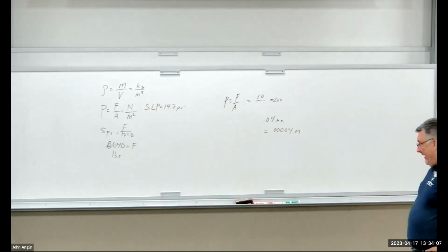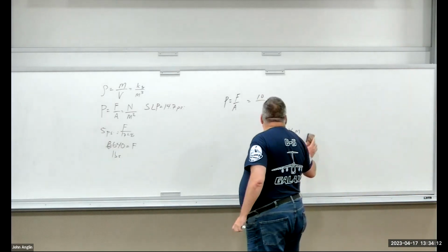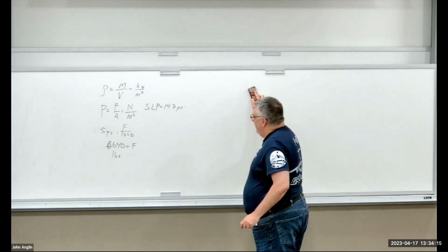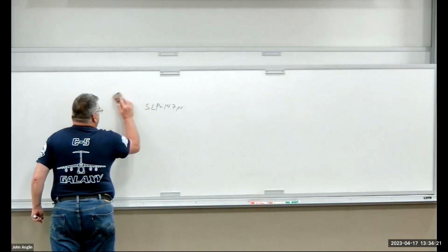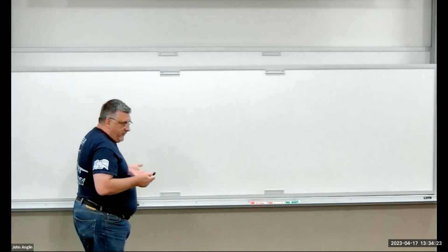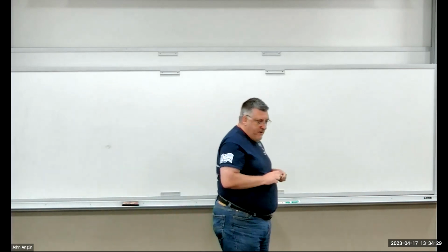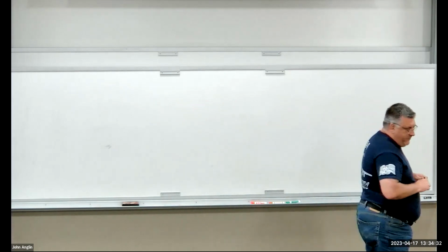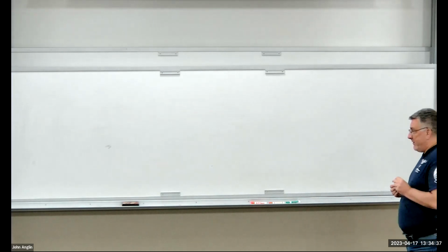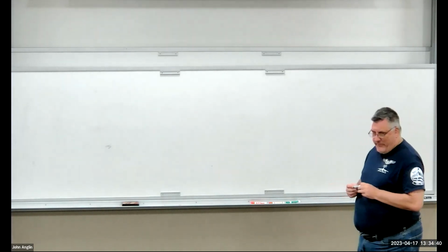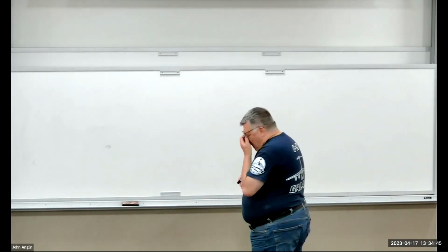This is a thing that we had to be careful of working on airplanes. We had hydraulic systems that ran all our flight controls, things like that. Now, remember I told you your typical car tire has an inflation pressure of about 32 pounds per square inch. On a typical aircraft, the hydraulic system is pressurized to 3,000 pounds per square inch. So it's 100 times higher than your car tire.